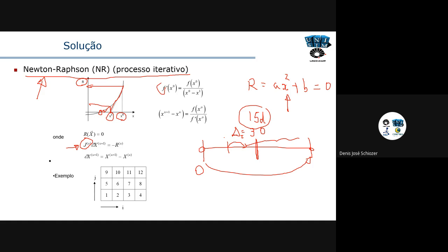I don't know if this is happening in your projects, but for complex grids and complex solutions, this happens many times in a simulation. It tries to solve for a time step. If I don't reach a solution, I go back to half of the time step and try again until we reach convergence. Once I have convergence, it starts the process again and so on. Okay?